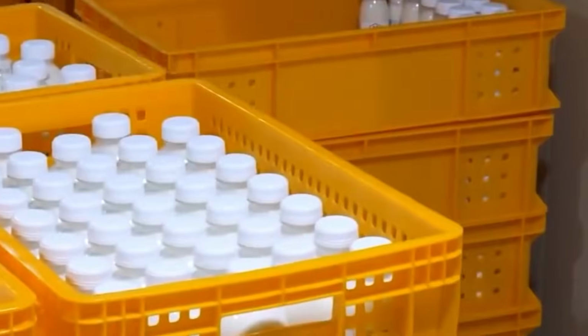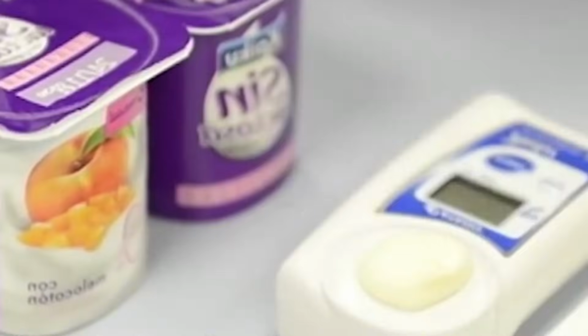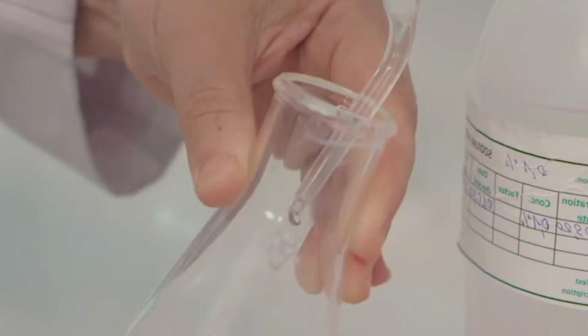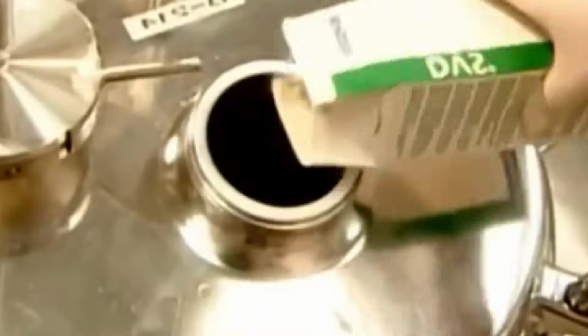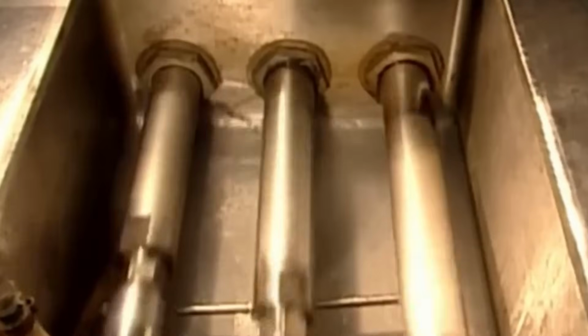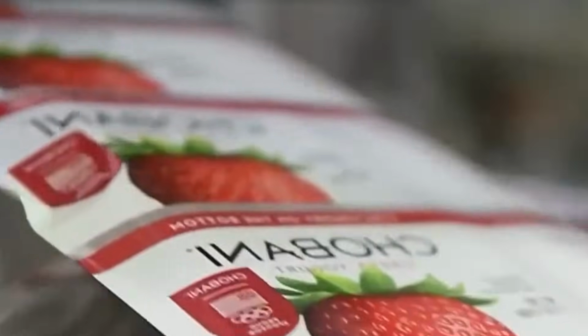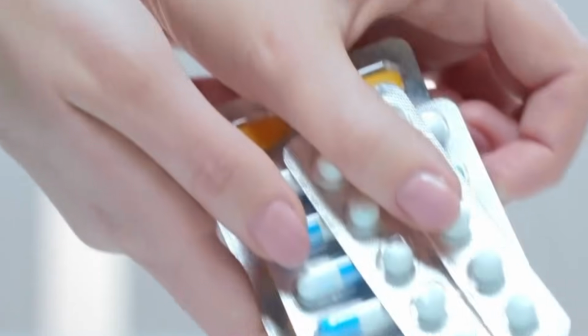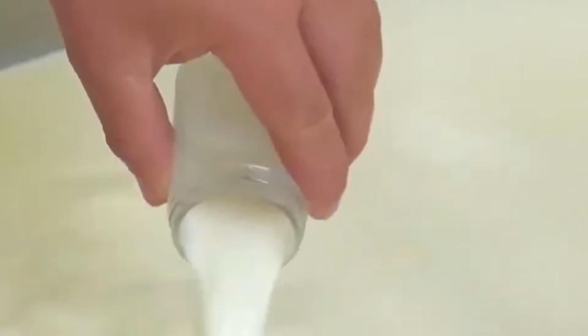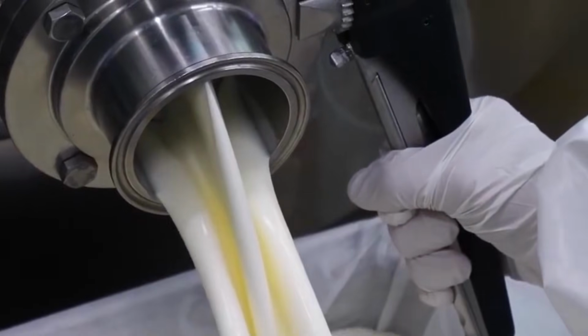Viscosity is monitored continuously via inline rotational viscometers, and any deviation triggers automatic adjustment to the water feed rate or agitation speed. Once all ingredients are combined, the resulting mix is pasteurized using a continuous high-temperature, short-time HTST pasteurizer. The pasteurization process typically operates at 85 degrees Celsius for 30 seconds to ensure microbial reduction without altering flavor or functional properties. The system includes balance tanks, timing pumps, regeneration sections, holding tubes, and cooling exchangers. Temperature probes and flow controllers verify that critical control parameters are met for every liter of mix.